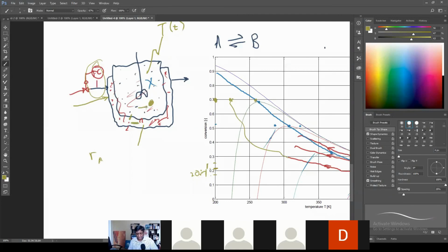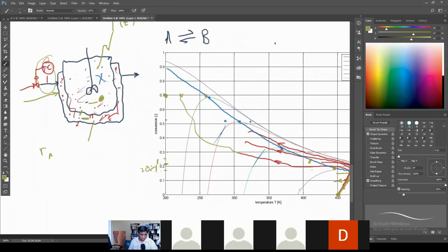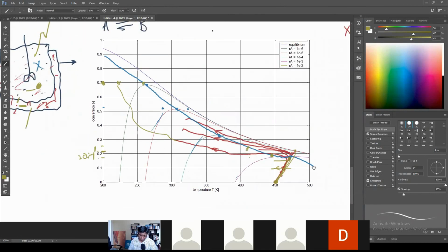So due to thermal lag, it might be that your flow rate changes are not fast enough. However, you can plan for that, right? You know the maximum rate path beforehand. Because you have the kinetics, you can draw your iso rate lines and you can get the maximum rate path. And if you know the thermal lag in your system, you can then apply flow rates far in advance of that.